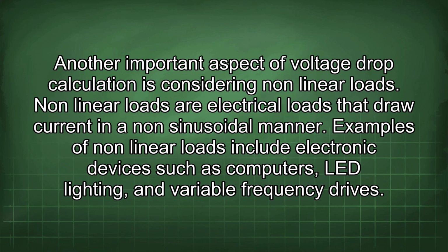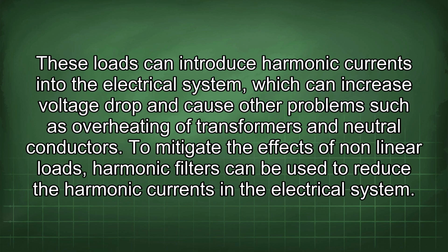Another important aspect of voltage drop calculation is considering nonlinear loads. Nonlinear loads are electrical loads that draw current in a non-sinusoidal manner. Examples of nonlinear loads include electronic devices such as computers, LED lighting, and variable frequency drives. These loads can introduce harmonic currents into the electrical system, which can increase voltage drop and cause other problems such as overheating of transformers and neutral conductors.